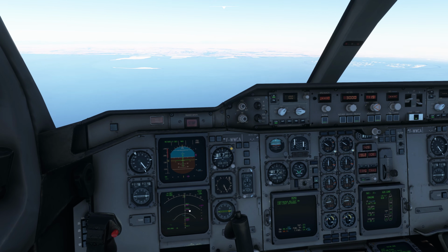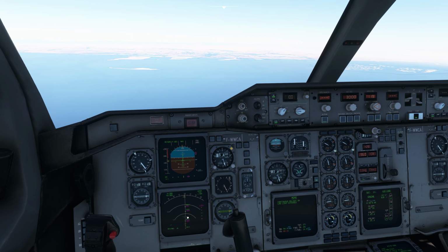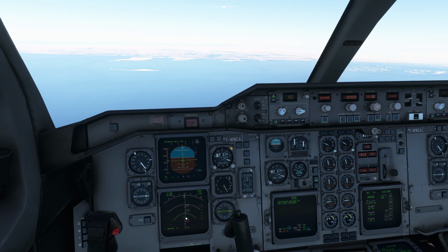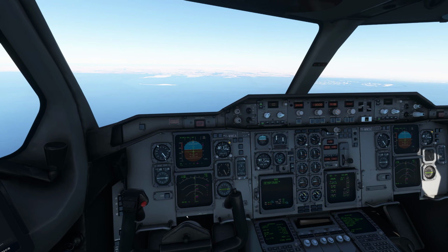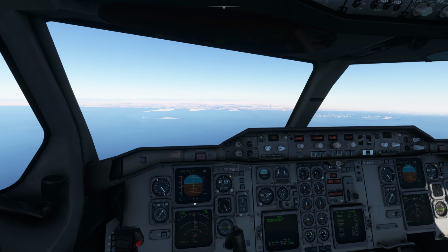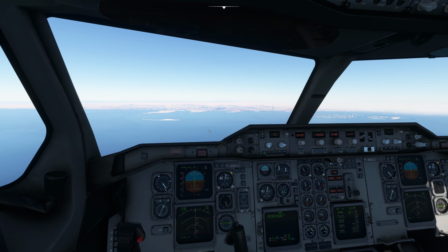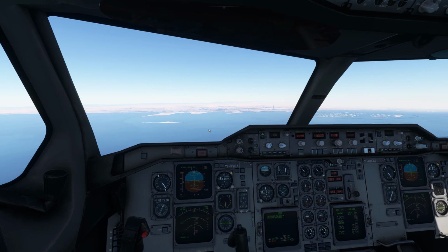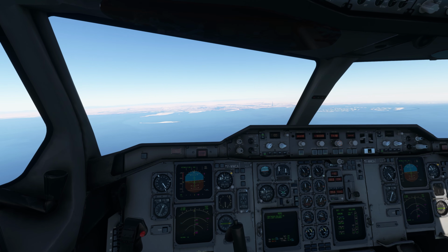Speed off 3,000 and above, and over here at this point DB657, I should be at 3,000 feet in order to intercept the glide slope. And as you can see by this arrow, I will be at 3,000 feet by this point, so it's okay. Now the plane will be leveling off at 3,000, just adjusting the course.